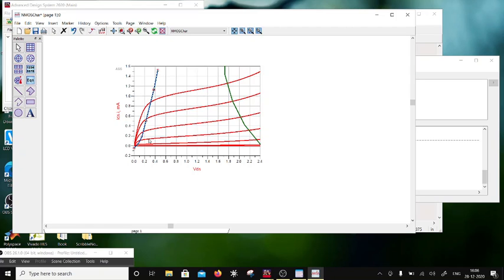If you want to use a MOSFET as a resistor, for example, then you can use this linear region, which is close here. It's linear, and if you go further, it will be a square law nature, and if you go further, it will be a linear nature due to channel length modulation, and if you go in this region, it is going to be the drain to bulk junction breaking down. So we are supposed to be operating here.